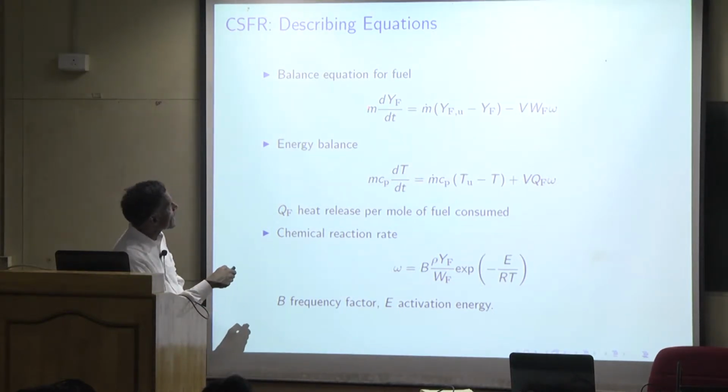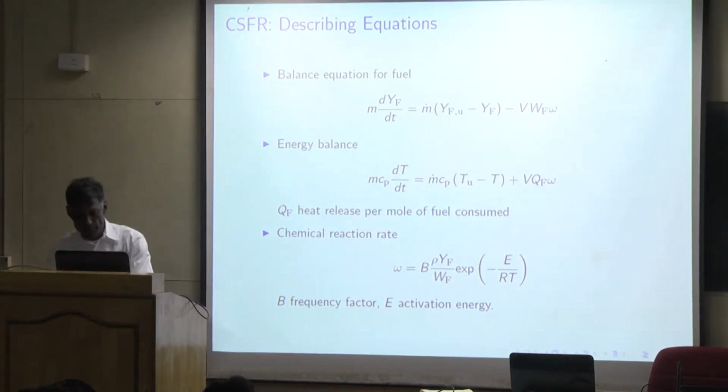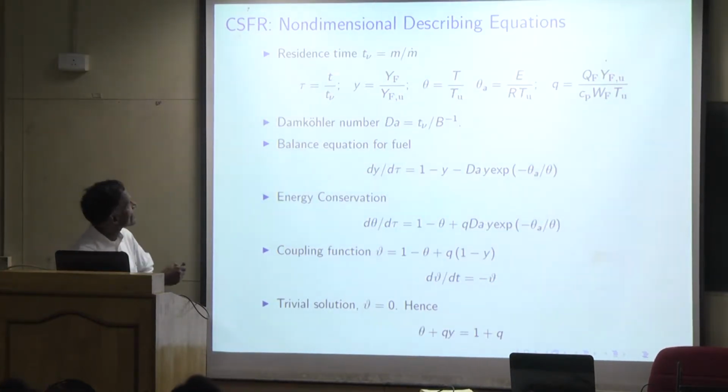So therefore, m divided by m dot, in fact, if you take the m dot and put it in the denominator here, m divided by m dot should be the characteristic time, okay? So in this problem, which is what it is, you define a characteristic time as T nu, which is the residence time. This quantity T nu is m divided by m dot, okay? So I've now selected the characteristic time, and you can now divide by this initial mass fraction of the